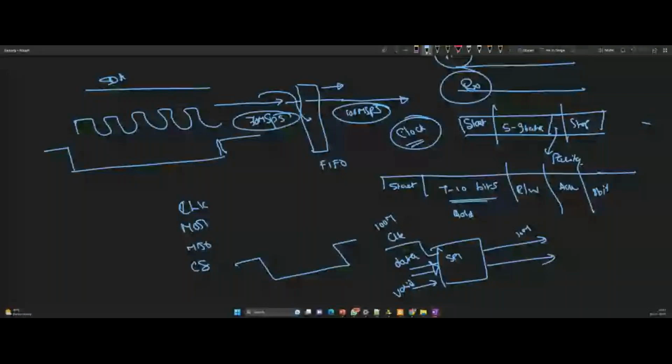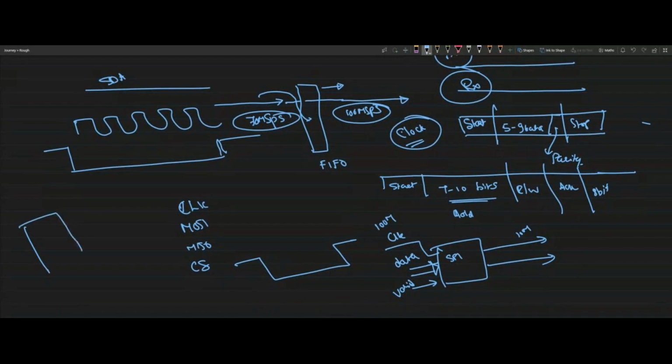So can you also give an idea of why we need a protocol for FPGA? We need to communicate from our design to an ADC, or from our design to some memory. For example, our configuration data is stored in some flash. All the permanent configuration data might be stored in flash.